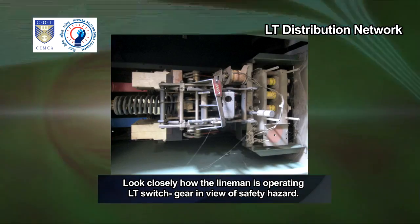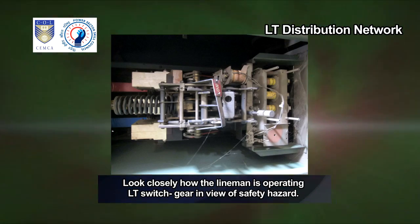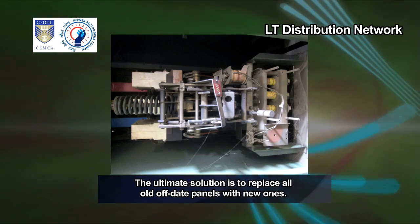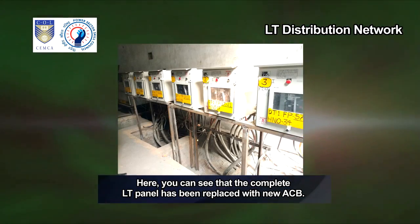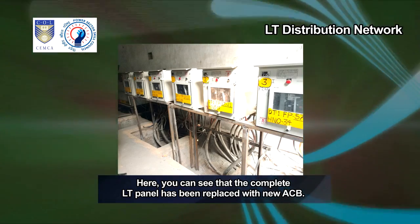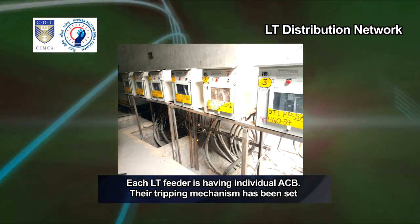Look closely now. The lineman is operating LT switchgear in view of safety hazard. The ultimate solution is to replace all old off-date panels with new ones. Here you can see that the complete LT panel has been replaced with new ACB. Each LT feeder is having individual ACB.